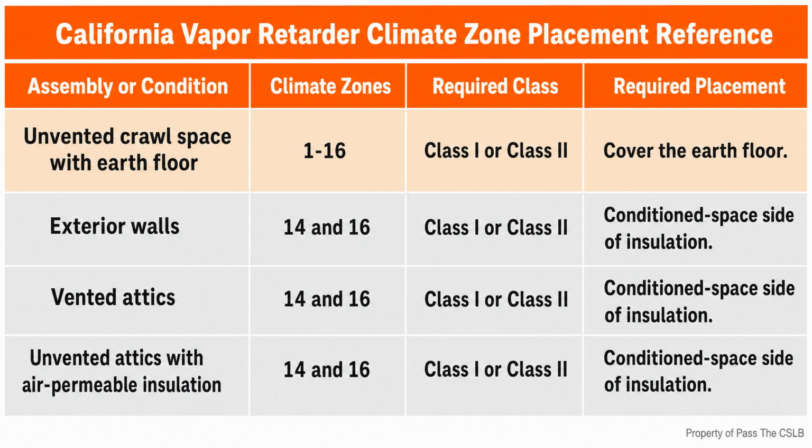This is also where the jacket analogy needs care. A breathable exterior water control layer may stop liquid rain while allowing some vapor passage. A vapor retarder is classified by how strongly it limits vapor diffusion. Calling both layers plastic or paper tells me almost nothing about their actual function. I need the listed properties, approved detail, climate condition, and location in the assembly.